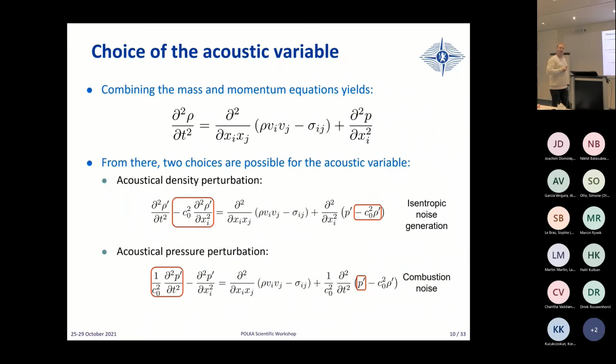So there is, it depends very much. The first approximation when you go through a contraction is that you have a different force. So you have to accelerate fluid with different density. And therefore, if you have the same pressure field, there is a kind of discrepancy between the acceleration of the hot fluid and the cold fluid. This induces a dipole. Yeah, typically the light fluid will accelerate faster than the...